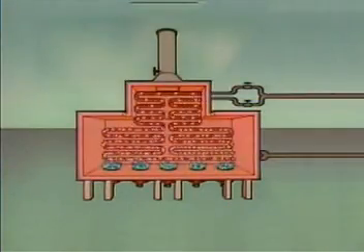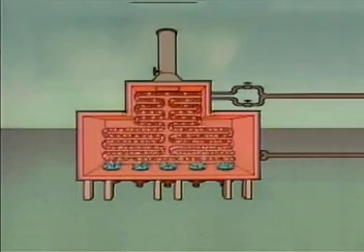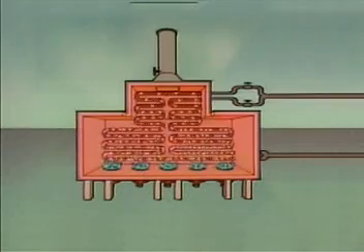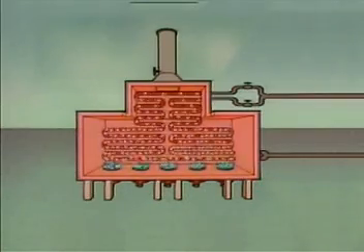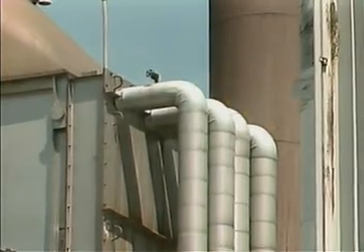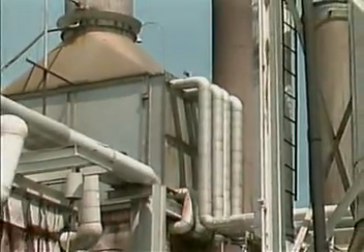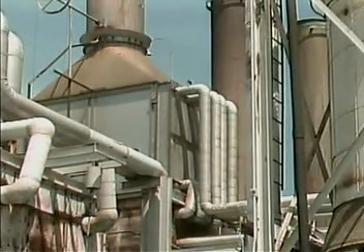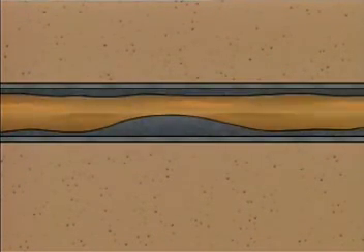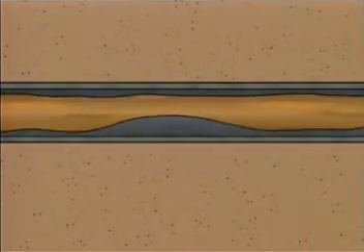In multipass furnaces, the flow of fluid through the tubes can present additional problems. In addition to flowing at the proper rate, the process fluid should move evenly through all of the tubes in the furnace. If the flow is not even in all the tubes, the fluid will not be heated evenly. As a result, the temperature of the fluid leaving the furnace may not be within the specified range.